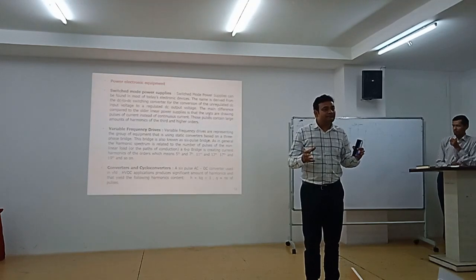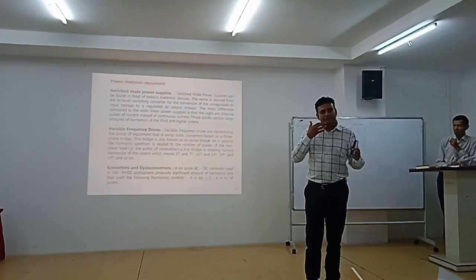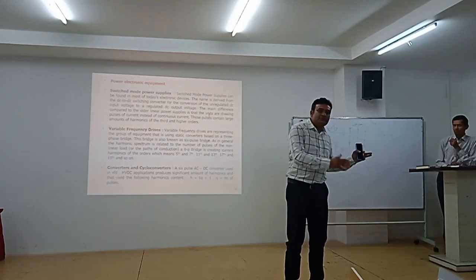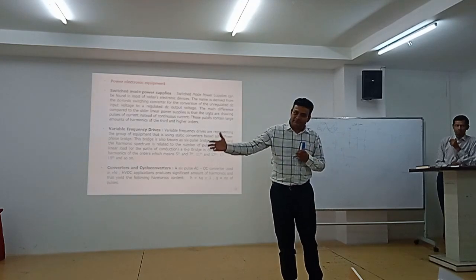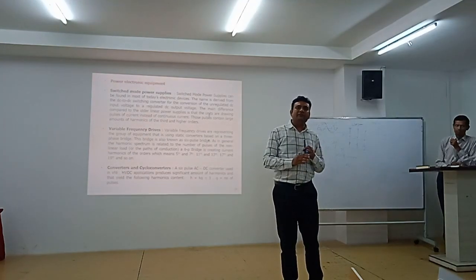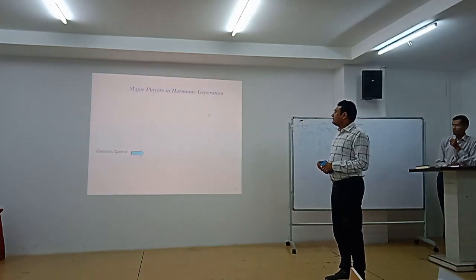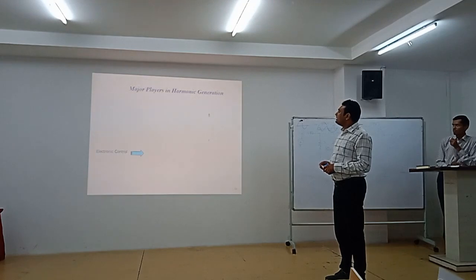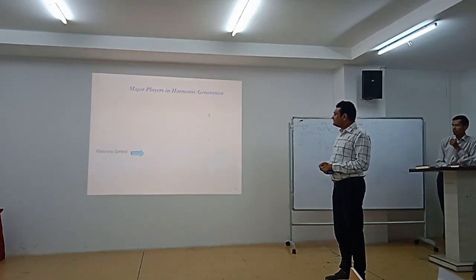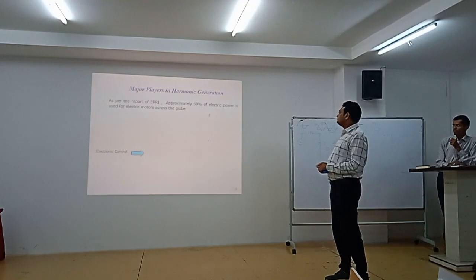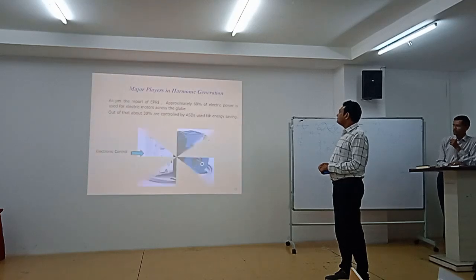What comes in a VFD? Switches, bridges. Bridges, right? It converts 3 phase to DC, and DC to 3 phase AC. So heavy non-linearity occurs, right? Next, converter and cycloconverter. Yes, the major player in harmonics generation is the VFD.